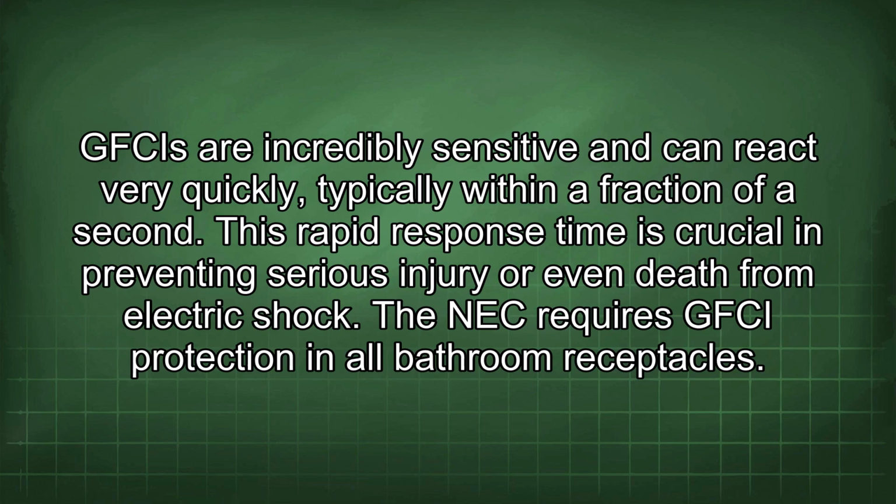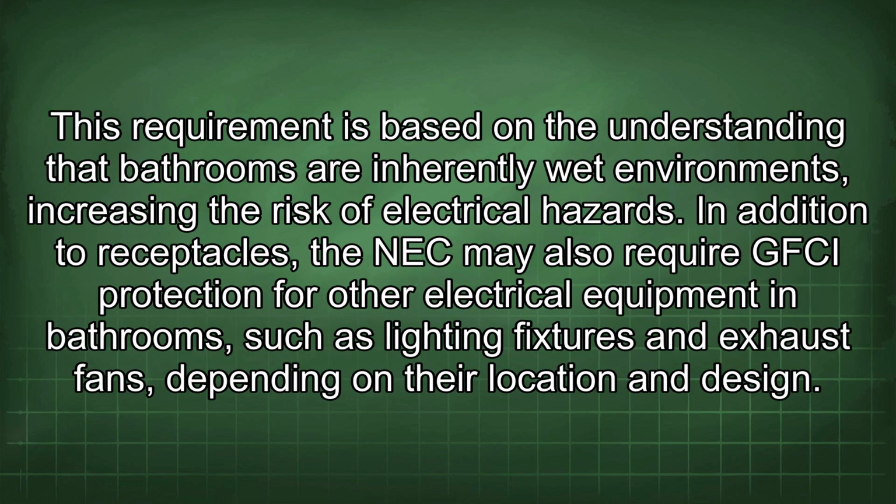The NEC requires GFCI protection in all bathroom receptacles. This requirement is based on the understanding that bathrooms are inherently wet environments, increasing the risk of electrical hazards. In addition to receptacles, the NEC may also require GFCI protection for other electrical equipment in bathrooms, such as lighting fixtures and exhaust fans, depending on the location and design.